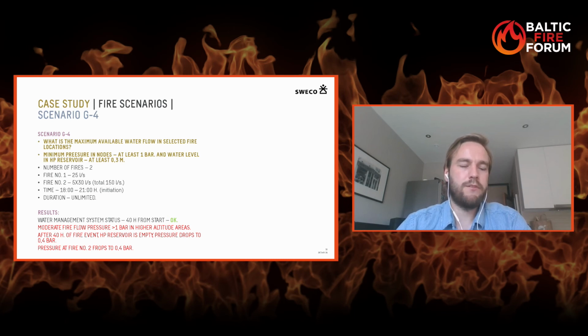But what happens after 40 hours? We have some problems there. We have moderate fire flow pressures, which are under 1 bar in higher altitudes, which is not good. After 40 hours from the fire start, high pressure reservoirs got empty, and the pressure drops to 0.4 bars. And pressure at fire number 2 drops to 0.8 bars.